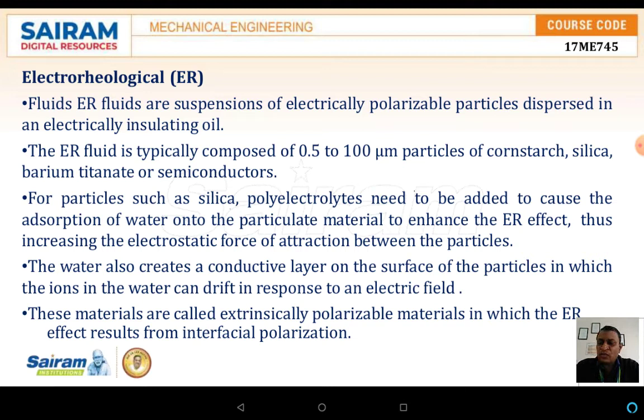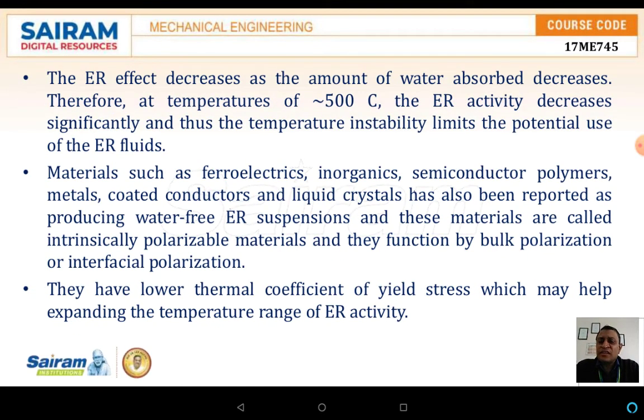The water also creates a conductive layer on the surface of the particles, in which the ions in the water can drift in response to the electric field. These materials are called extrinsically polarizable materials, in which the ER effect results from an interfacial polarization. The ER effect decreases as the amount of water absorbed decreases.